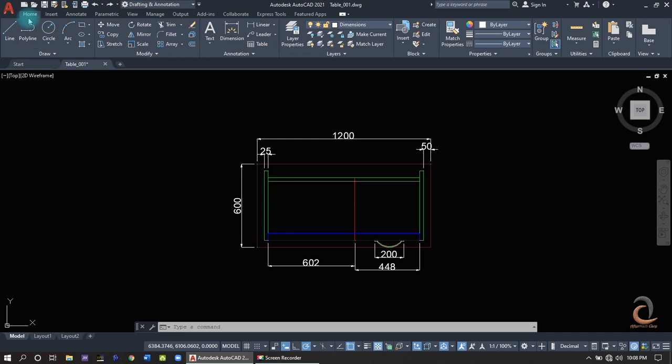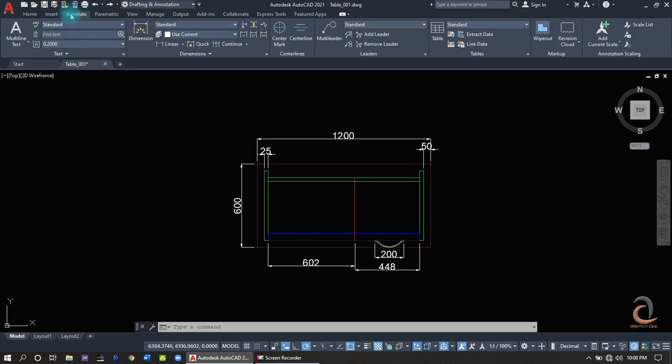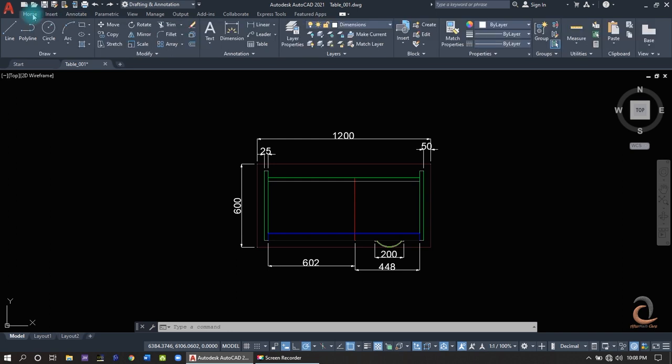Below the toolbar is the ribbon. Now AutoCAD has organized the ribbon in an easy to access manner by dividing the ribbon into tabs. The tabs are named based on each task. For example, to insert something into our drawing, select the Insert tab. To find more annotation tools, which are not in the Home tab, click on the Annotate tab and you will find them too.